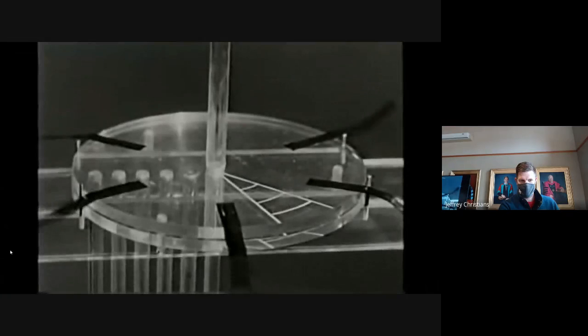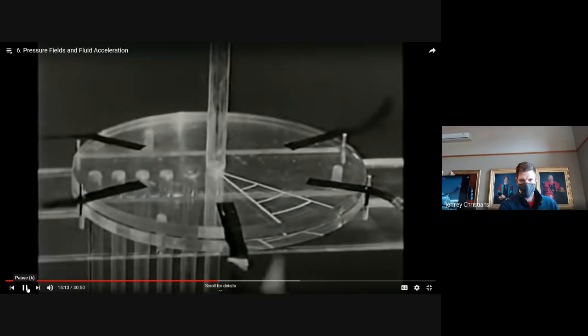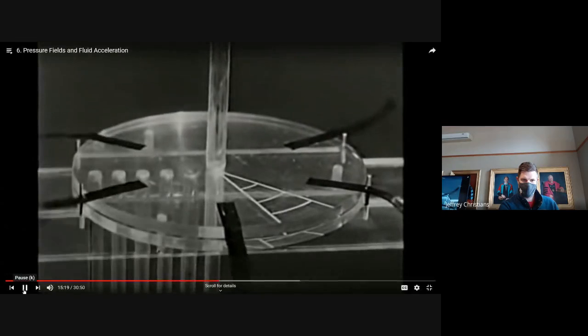The reason for this is that the through-flow cross-section area between these increases with radius. This area increase causes a fluid deceleration, and by reducing velocity, pressure rises. Isn't that wild? So force is equal to pressure times area. You have a really small spot in the center at high pressure, which is pushing the disc away. But most of the disc is actually below atmospheric, so that's trying to suck the disc up. So the net effect is that you're blowing air out and you suck the disc up. Kind of a wild effect.